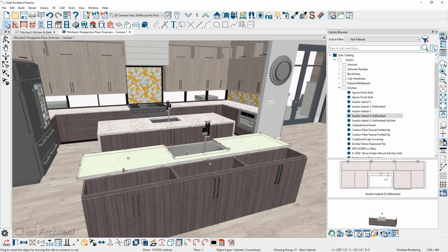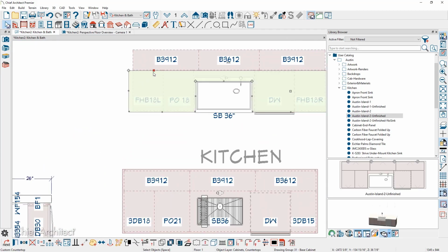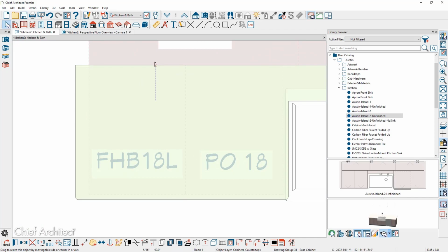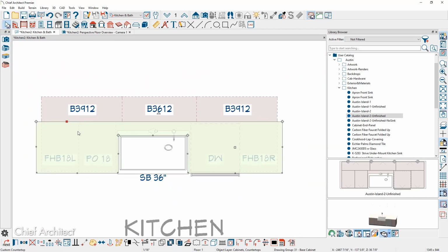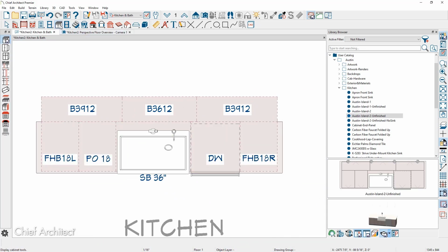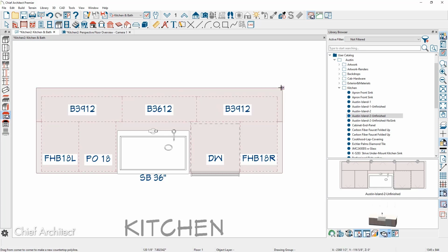It's going to be a little easier in the floor plan view to snap that countertop back exactly. Let's zoom in, and I'm going to pull and snap that exactly to the edge of the other cabinets. And then as I zoom out a little bit, I'm going to use the custom countertop tool found underneath of the cabinet tool. With the custom countertop tool, I'm going to come over here, pick up the snap on the edge of the countertop, pull over, pick up the snap on the other side, and then generate the initial custom countertop.